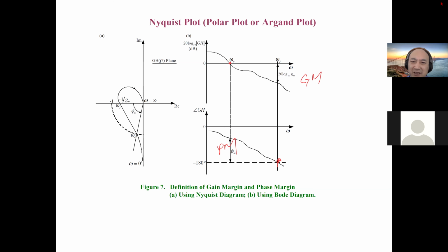So that is called a Bode plot. It is possible that you can put the magnitude and the imaginary and the real part. Let me show you one thing. You have 1 divided by tau s plus 1. If I draw the Bode plot, you know the Bode plot is something like this. It's from 0 dB to a point, then you go down, and this one is 0 degree, then you have minus 90 degrees.